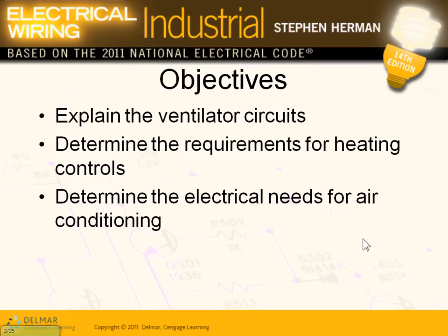it's going to have three mechanical systems. You're going to have a heating system to heat the building. You're going to have a cooling system to cool the building, and coupled with the heating and cooling, you're going to have some type of ventilation system so you can maintain a certain air exchange between the inside and outside of the building, so the mold can't grow inside your house or your building. So that's a big deal. Air exchange, they call it.